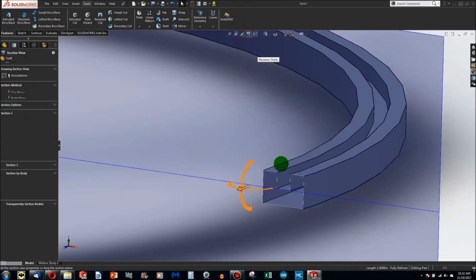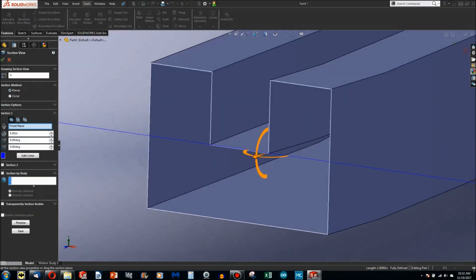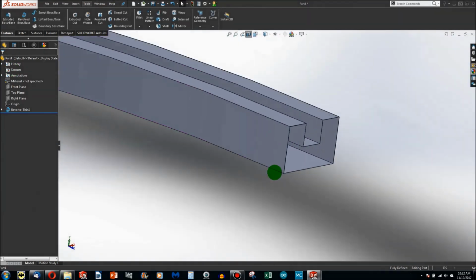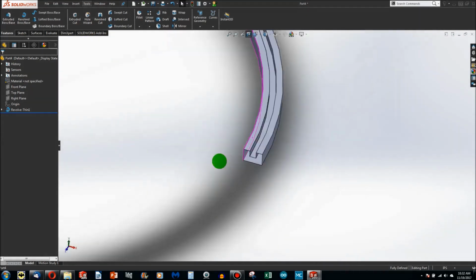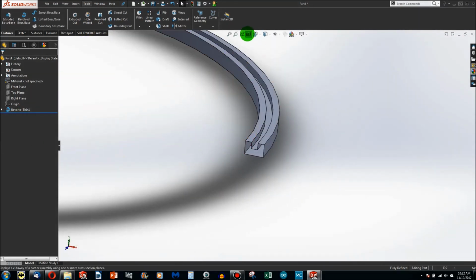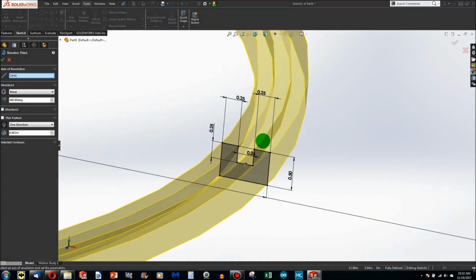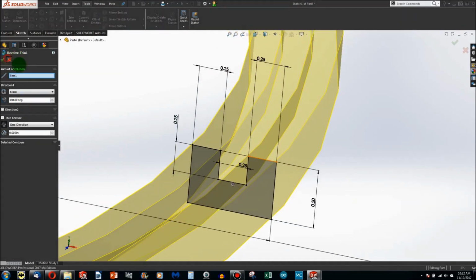And when I section it out, you can see that it made it a hollow thin feature 2/1000 of an inch thick. So you can do the thin feature if you want to make some hollow features. Thin features also work on a non-closed sketch.